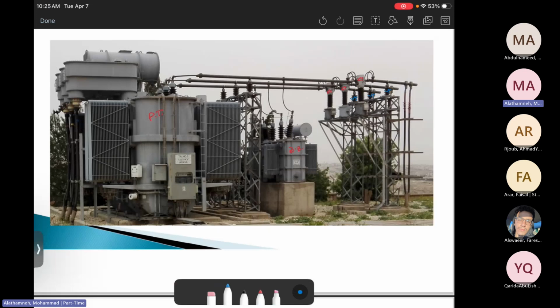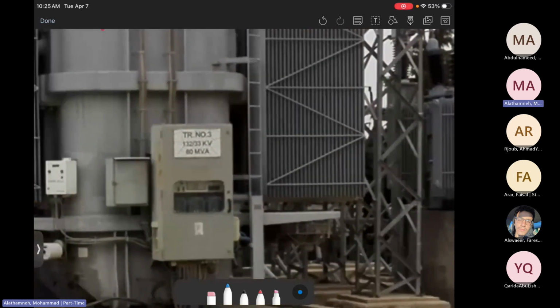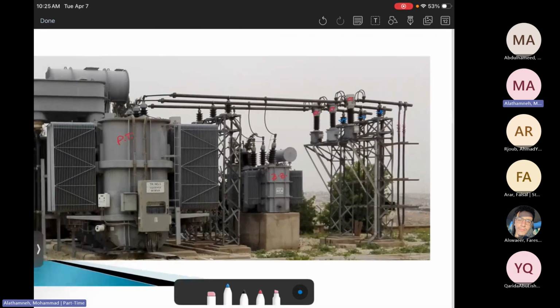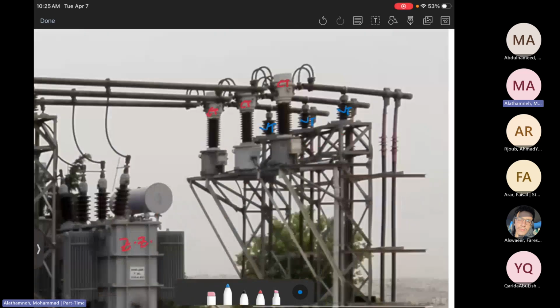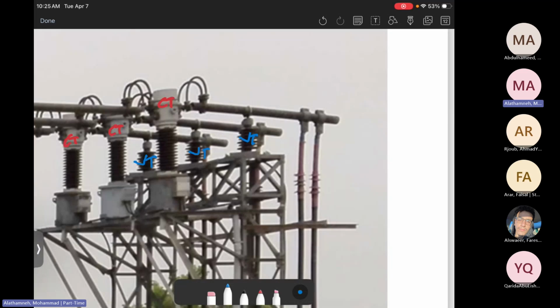And when you go into the field, you should be capable of determining or understanding the type of the transformer. Again, the power transformer is the largest one. Why is it big? Because it has very high ratings, for example, 60 megavolt ampere, while the zigzag transformer has a very low value. That's why it's smaller. CT and VT are very small instruments because they are used for measurement purposes, not to power up devices.